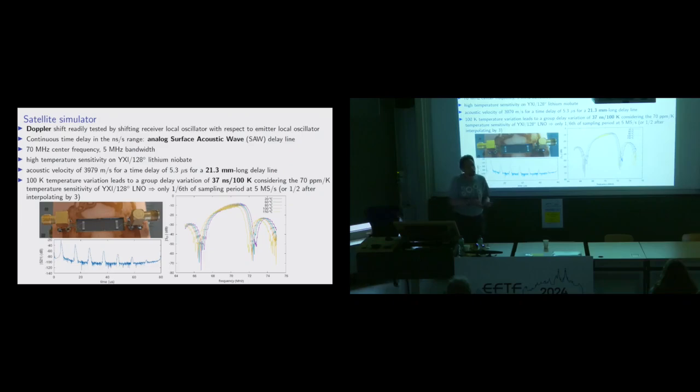And that's where, going back to the good old analog signal. Historically, our lab was doing piezoelectricity and acoustic delay lines. And so I asked my colleague, William Dagneau, to design a 70 megahertz surface acoustic wave delay line. It's kind of big, it's 21 millimeters long, because we're using temperature drift here. Lithium niobate has a high temperature sensitivity, and if you want to introduce a few tens of nanoseconds time offset continuously as you're moving the temperature, well, you need kind of a long time delay.